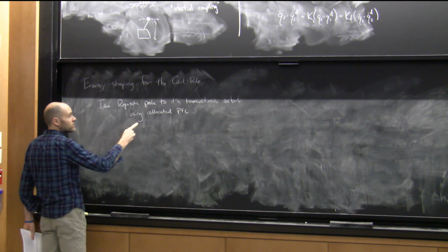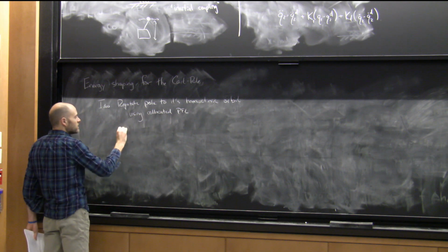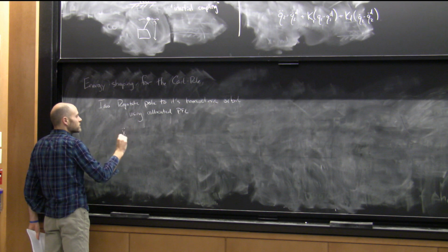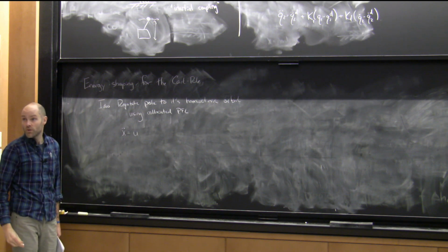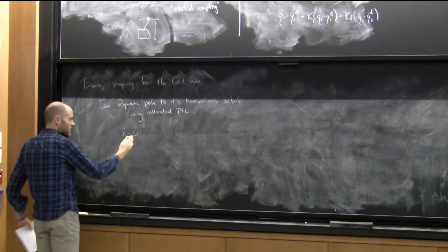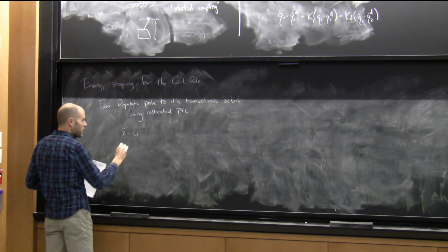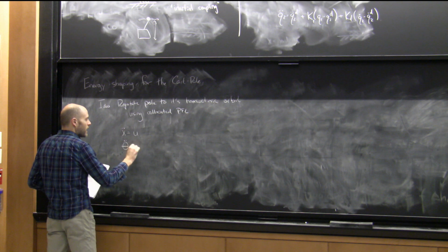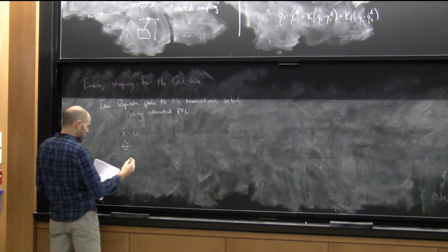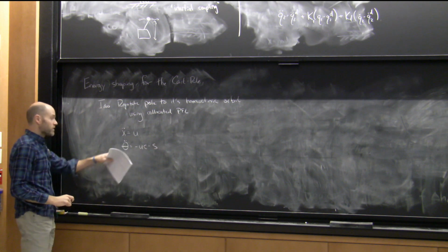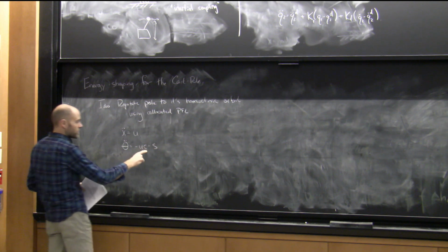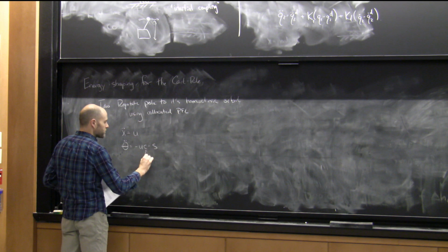So after the co-located PFL, the equations of motion of my cart pole were that my cart was perfectly controlled with whatever my input was. This is my feedback linearized input. And I was left with some nonlinear terms in the dynamics of the pole. This is cosine theta, and that's sine theta, my shorthand.